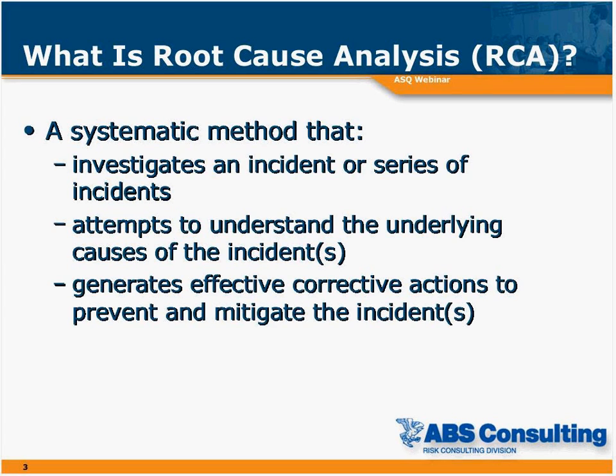What really caused the incident to occur? Not just the superficial equipment failure, but what really caused those equipment failures to happen. The goal is to generate effective corrective actions to prevent and mitigate the incidents. We want to spend our money wisely. We want to make sure that we understand the incident and that our corrective actions match up properly to the causes.